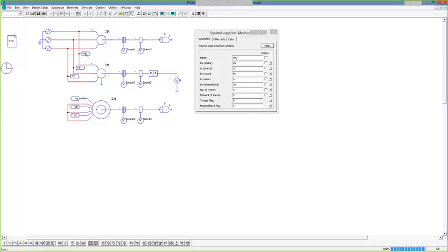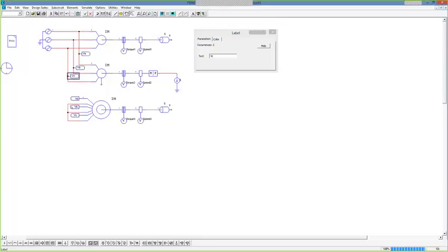We can also see that I've driven this with labels. So in PSim, you don't have to connect everything up. You can connect things with labels. Another thing to highlight is that wires only join if they've got a dot. So if you start the end of a wire on another wire, they'll connect. But if you cross the wires, they won't connect when you're wiring up.